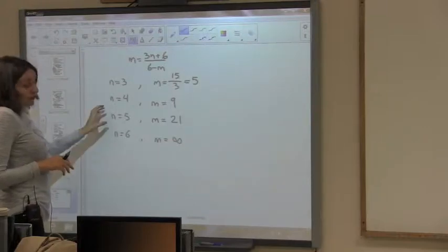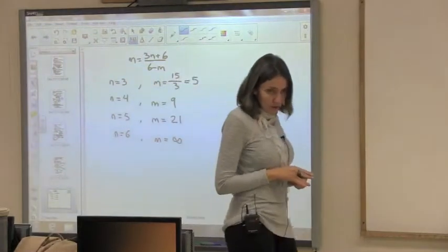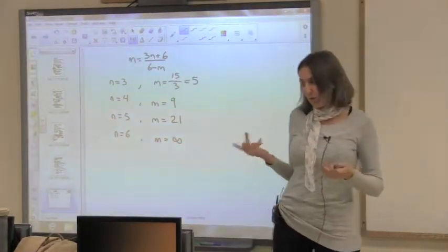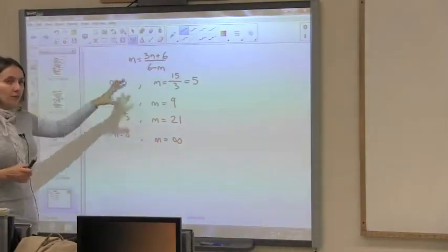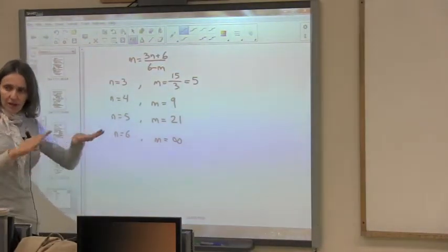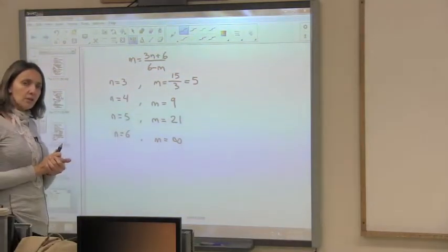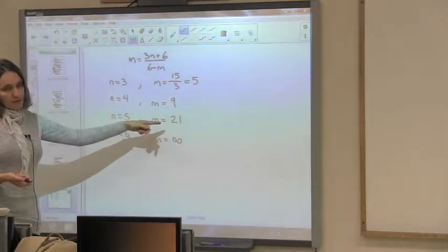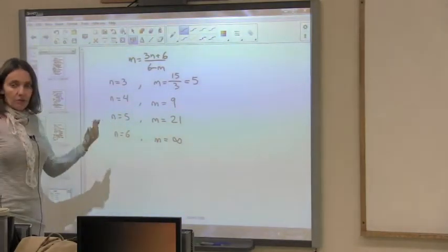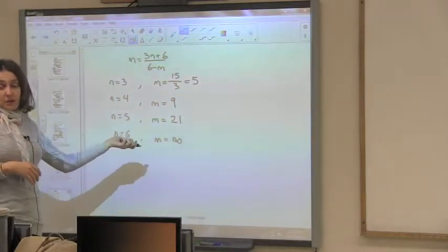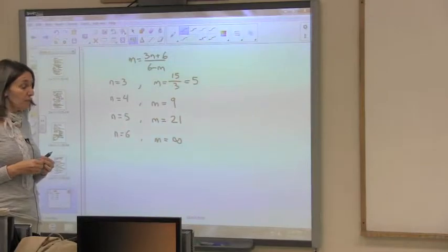The 4 and 5 degree of freedom serial robots are fairly common in industry. Not so much the 2 and the 3, but the 4 and 5, 4 mainly for working on subspaces like in planar, SCARA robots and similar. 5 are pretty general robots, and it's good to realize that you cannot just buy your robot and expect it to perform anything, because it won't be able to perform anything. It's limited.